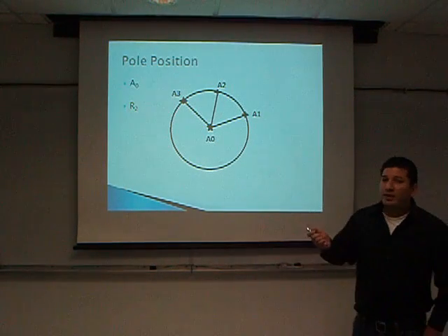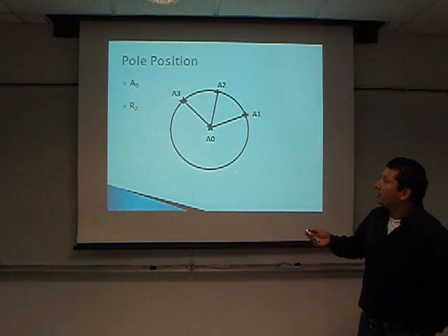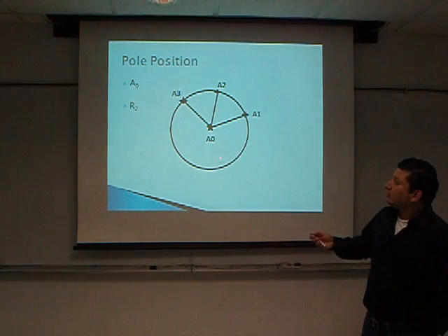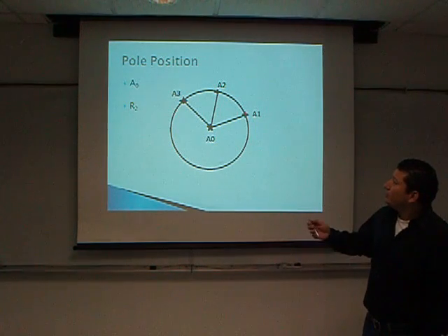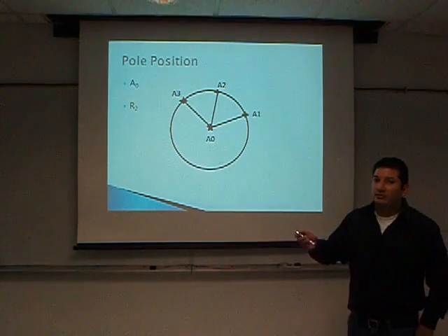From them, we were able to ascertain where pole A0 was, which in our case lies at the origin. This defines the crank aspect of the slider crank mechanism, with positions A1, A2, and A3, and R2 resulting in a length of 9.99 inches.